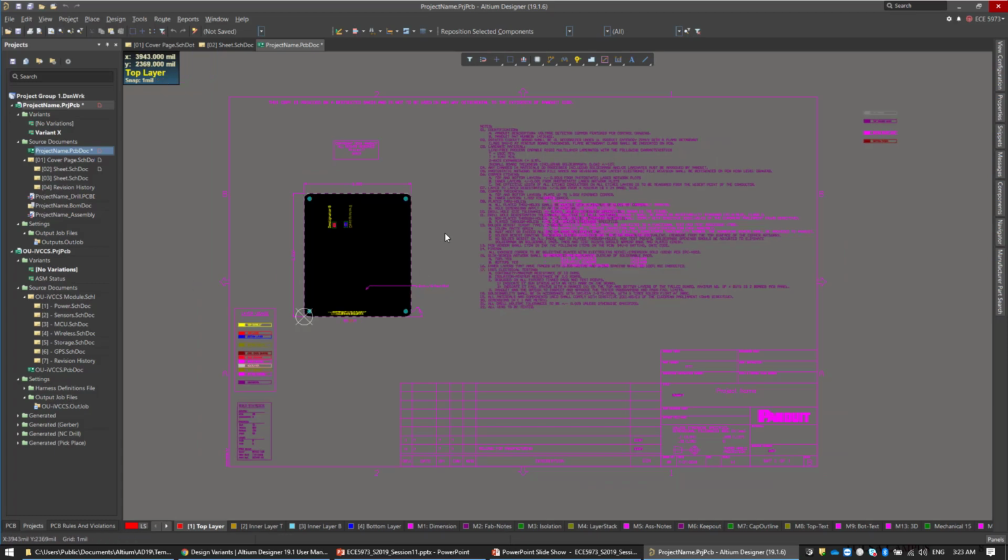And by default, this layout, as you can see, is for 4 layers. I have another layout for 6 layers, another layout for 8 layers, and these are templates. You don't have to design the layer stack at the beginning and put that. No, they are pre-designed. Now, if you want to change the layer stack, you can change it through the design, but you don't have to start from scratch, because you have a point you can start from. And this will be very helpful and will save time for the engineers working in the company.